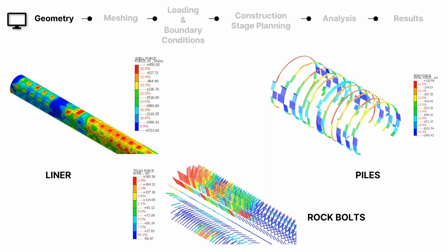Now coming to a brief glimpse of the results to be expected. The hoop force on the liner, and again this was the shear zone. You can see it is highest in this part, and I have installed steel arches. So steel arches will range from this part till this part. They are placed at a distance of 2 meters to 3 meters each, depending on the location or their degree of closeness to the shear zone, or their presence either inside or outside the shear zone.